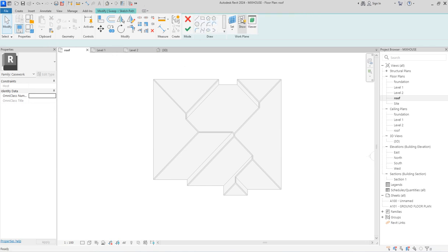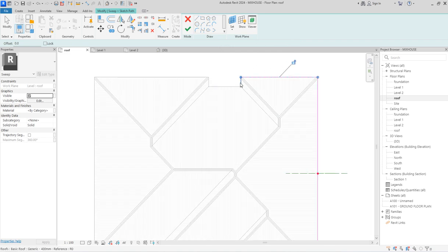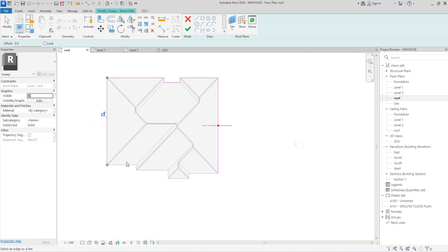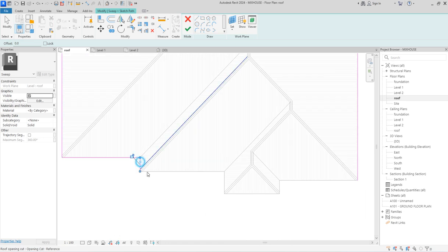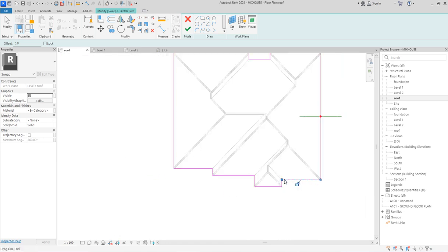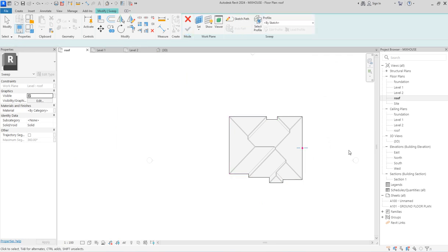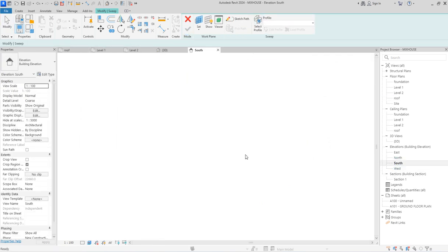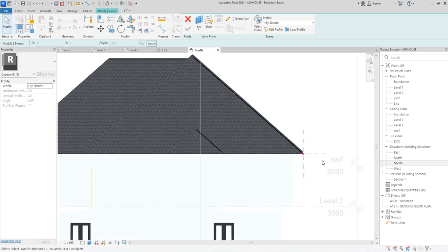Clicking sweep, then you click on sketch path. From the sketch path now, pick a point. So pick points. From the key point now, you start working on it generally. So I'm selecting this. Click all the paths in which I want the drawing to go. You can study this carefully so that all your lines will not be intersecting or interlooping. So you have a clear goal of your design straight up. So click finish. From here now you can go to start elevation, wait consistently until this one is opened.